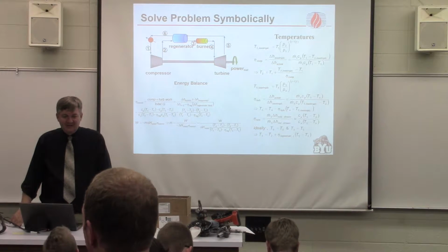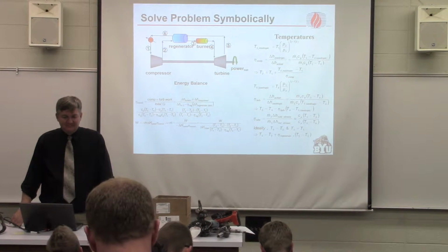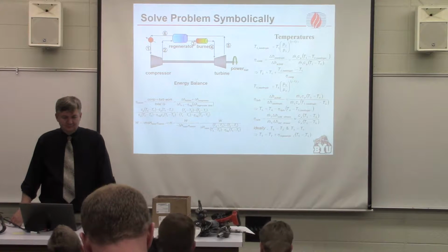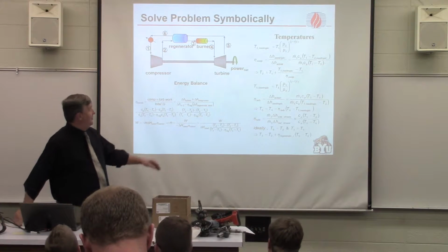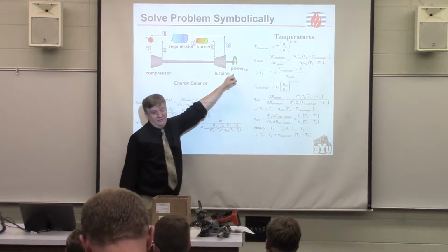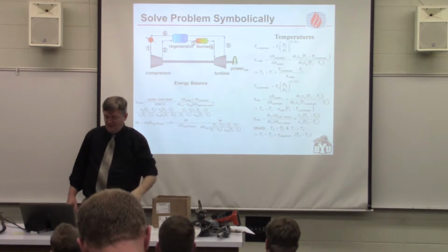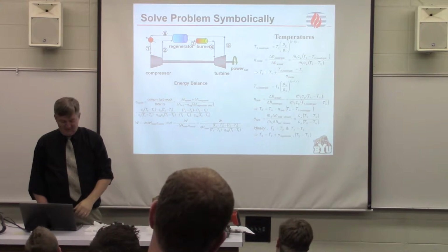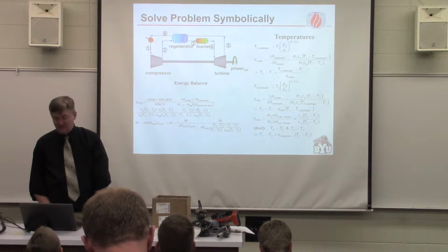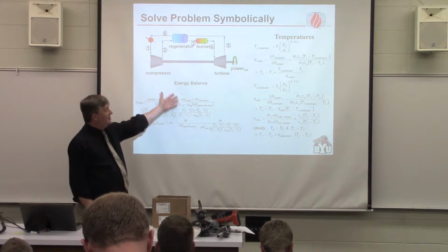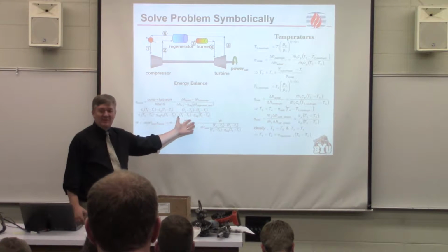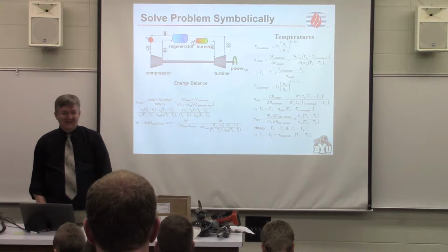Yeah, so in this case, we know the pressure ratio, so we're assuming it's pressurizing up to that pressure in the compressor and then the exact same pressure reduction for the turbine. Yes, so the only pressure changes are across these two devices, so they're linked together. That's part of this air standard cycle that is used for analyzing these kinds of things. This is a reasonably sophisticated analysis and actually comes out to be pretty simple if you make these kinds of engineering assumptions.